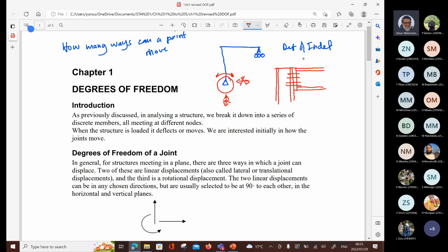But when we look at it through there, then you're going to see that you have the beam. Sorry, the drawing is a bit crude, but you have the beam and you have the plate, which is welded to it. And then those bolts in the background. So that's what it looks like. So this gives you a more fixed connection. So this one will be fixed. Right, so that's like a fixed connection. And of course, the pin I showed you earlier.